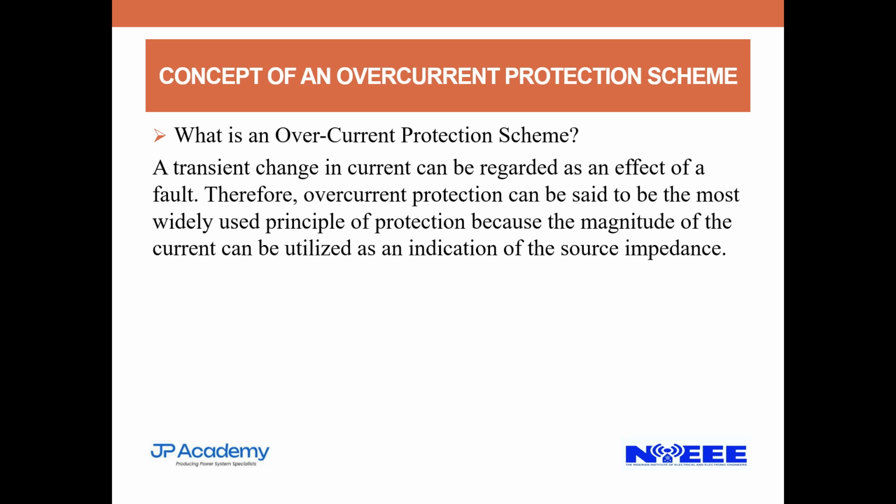Is it above my set point? Is it below my set point? If it is above my set point, I'll send the information to the protective relay. The protective relay will send the information to the circuit breaker. That is basically how the overcurrent protection scheme works.